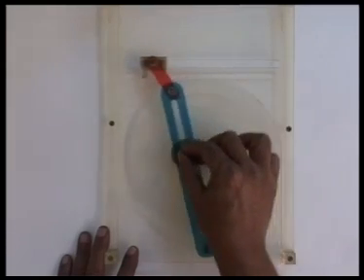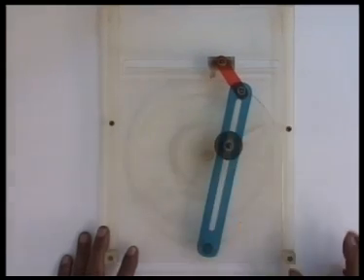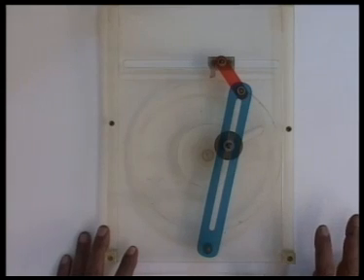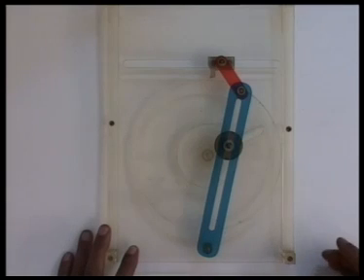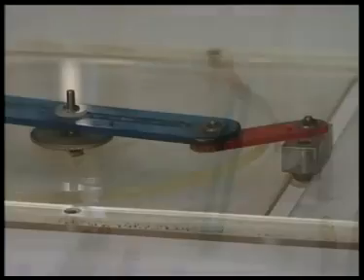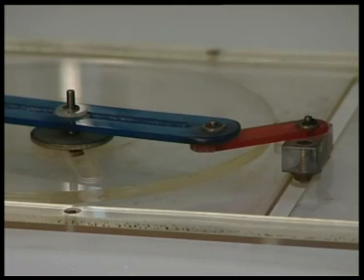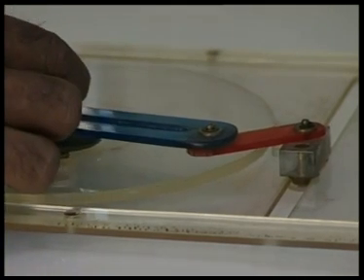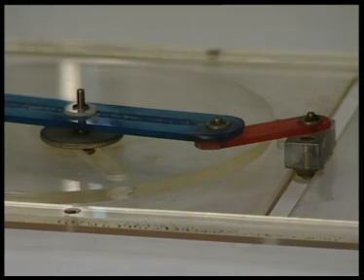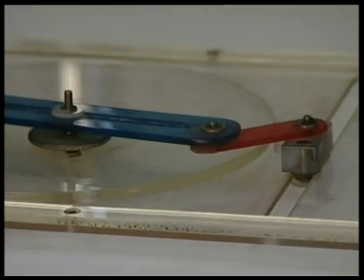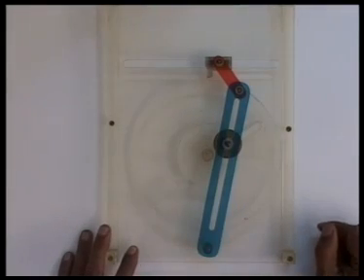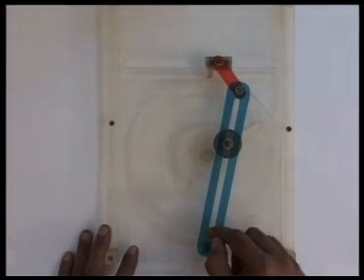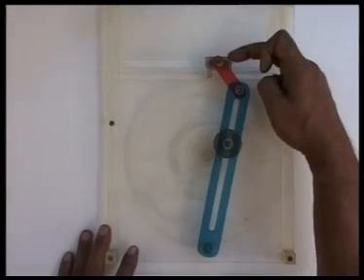So, they do not always remain coincident, but for the purpose of kinematic analysis, it will be very useful to consider the velocity and acceleration relationships between these two instantaneously coincident points, say A2 and A4. So, this is the problem which we will be analyzing now. Suppose the angular velocity of this body 2, that is the bull gear, is given and assumed to be constant. Let us find out at this configuration what is the velocity and acceleration of the tool holder.